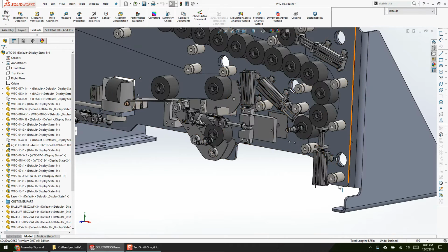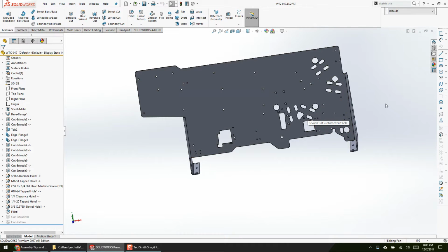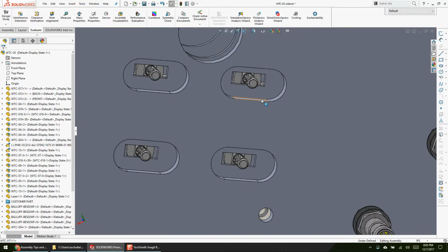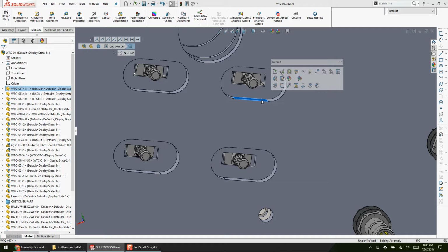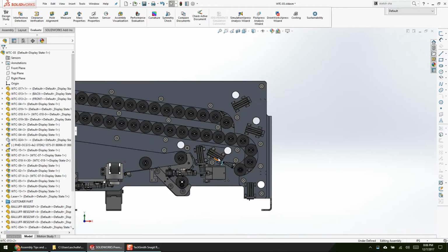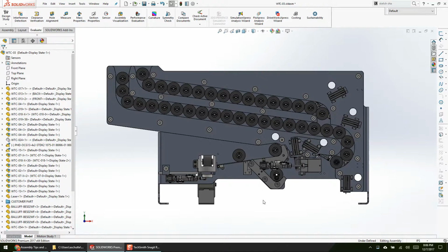I don't know how I got in the fillet tangent, but we're off of it now. Okay, so we've got to design a few other things. I knew we had access problems, so we slotted out everything so I can now loosen these bolts and adjust my cylinders all without taking the machine apart. Big, generous clearance holes when and where able to be able to put hoses and wires and access these different things. So even in the design, we're trying to limit our liability and maximize our productivity in the SolidWorks environment, but it also transcends into the machine design environment or the product design, whatever you're designing, and thinking beyond CAD.